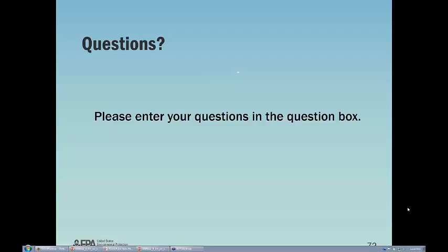Great. All right. Kind of carrying on here. What are your thoughts on the pros and cons of simulating zooplankton as state variables? Hello, Greg. I tried to call you last week to answer this question. This is one way to get the question answered. We've tried to incorporate mechanistic zooplankton models into our water quality models, and it's been less than fruitful for a couple of different reasons.